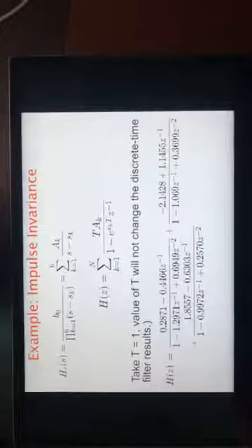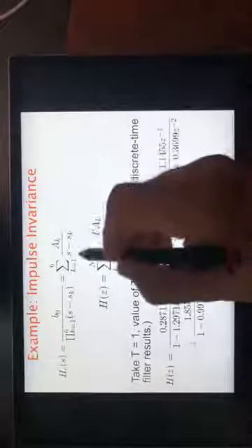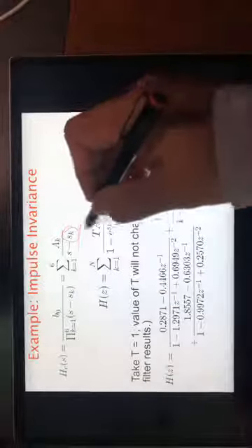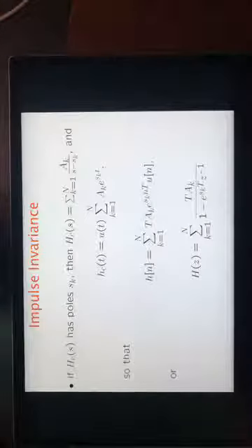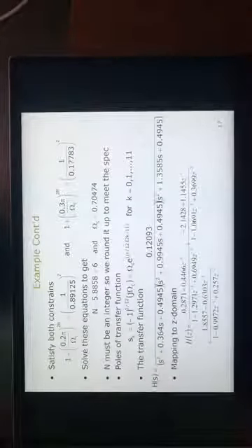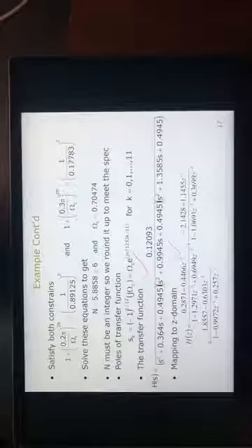So this is the impulse invariance. Okay, and if you remember, in impulse invariance, the transformation was simple, that s_k gets mapped onto an exponential. Okay, so a transfer function would change. So this is the same example done for the impulse invariance. You have an H of s, and H of s is converted into H of z by that transformation, which we have seen.